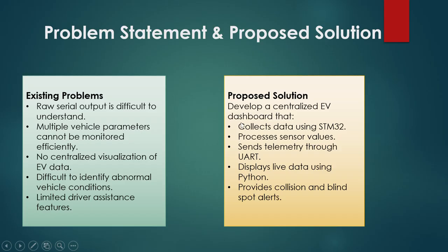To solve this, I developed a centralized dashboard where the STM32 Blue Pill reads sensor values, processes EV parameters, performs ADAS calculations, and transmits the data to a Python dashboard through UART. The dashboard then displays all information graphically in real time.